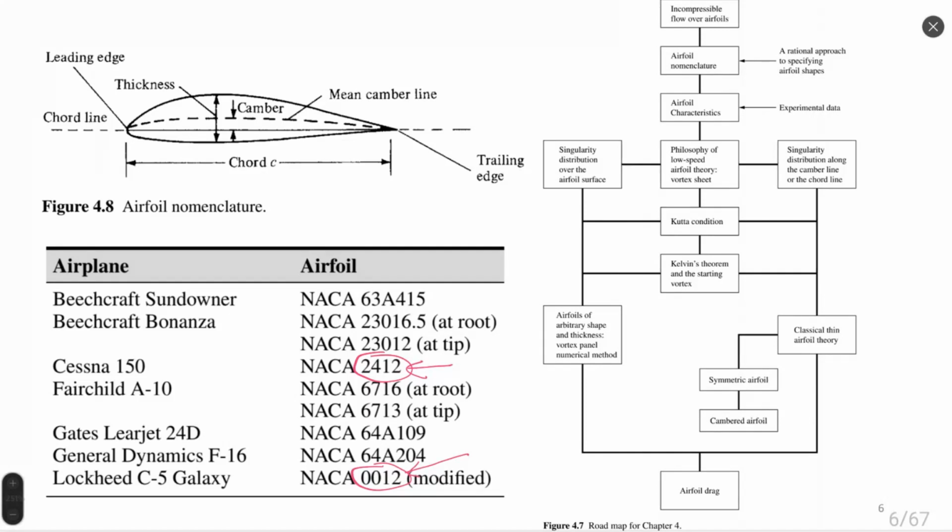Symmetric airfoils are quite nice, and they are widely used for tails, for example, or for mechanisms which require a definitive value of lift with respect to angle of attack, whereas non-symmetric airfoils are very good for creation of lift and very good for lift to drag ratio. So depending on what we need, we choose our airfoil.